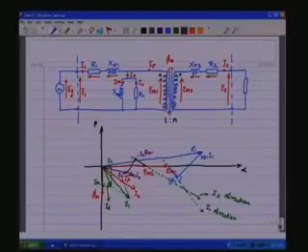So, this would be the phasor diagram of this complete equivalent circuit of the transformer. Though in the completed form the phasor diagram looks complex, but it is not so. You can start from the idealized transformer which is how we evolved the circuit, and then the core loss component, the magnetizing component, and then follow it up with the leakage components and the winding resistance components that we added to get the complete phasor diagram of the transformer.